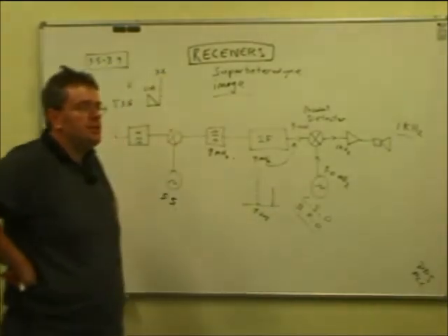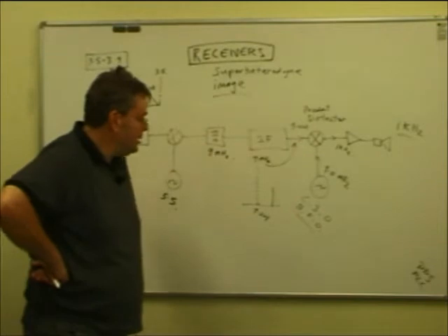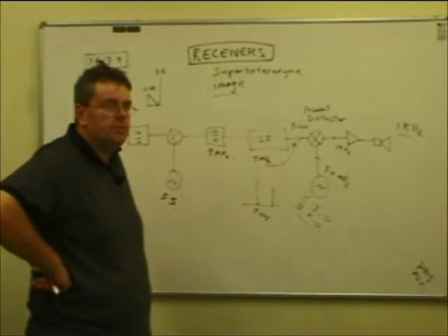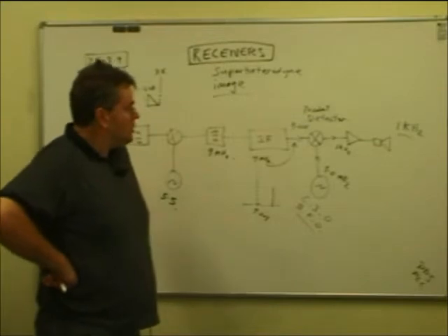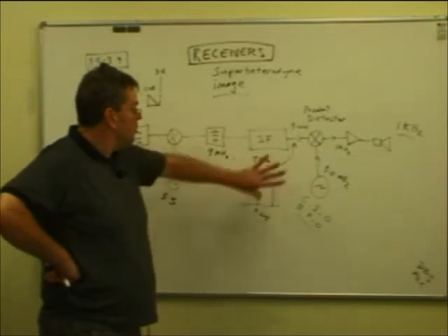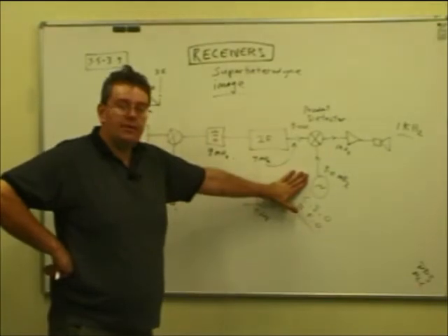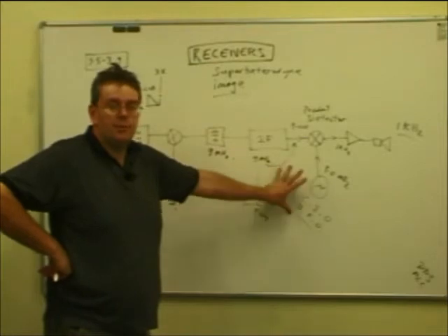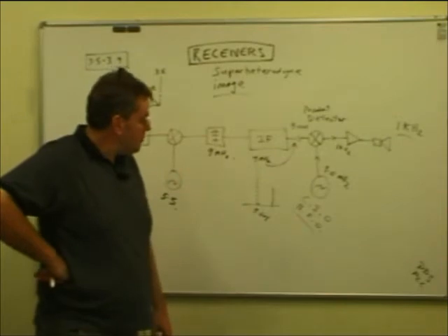It was originally called a beat frequency oscillator because people used to call combining 2 tones together beating them together. The other term that you'll see, which I think is more self-explanatory, is carrier insertion oscillator. You're re-injecting the carrier back in as you receive it. This is why single sideband receivers are quite a lot more complicated than a straightforward AM receiver. For an AM receiver, all you need is a diode detector arrangement and off you go. Single sideband, you have to put a second oscillator in here and a second mixer. This oscillator is generally crystal controlled. It has to be very stable, otherwise it will cause quite significant problems to the operation of the receiver.